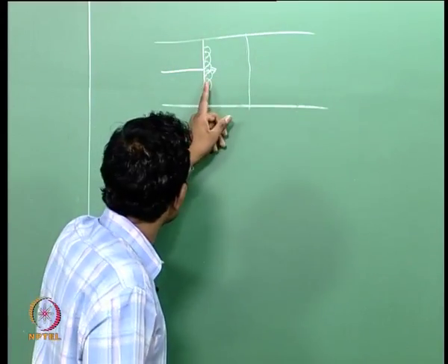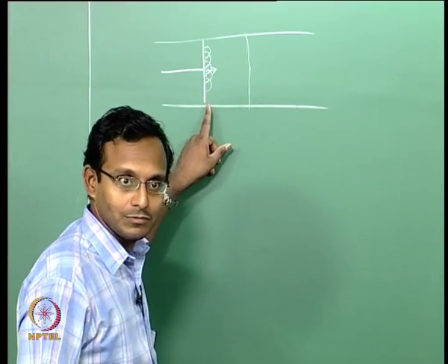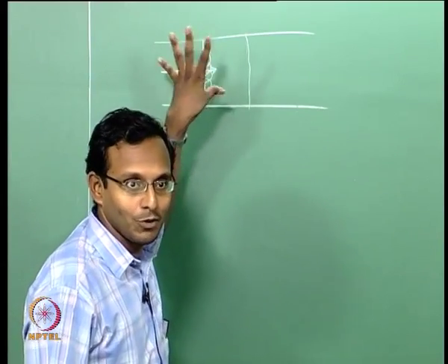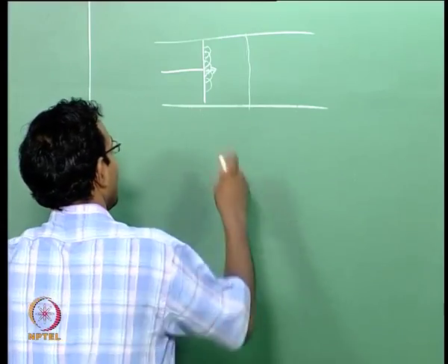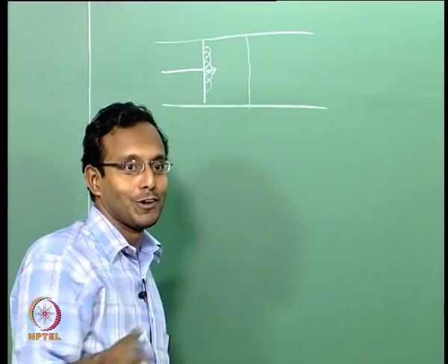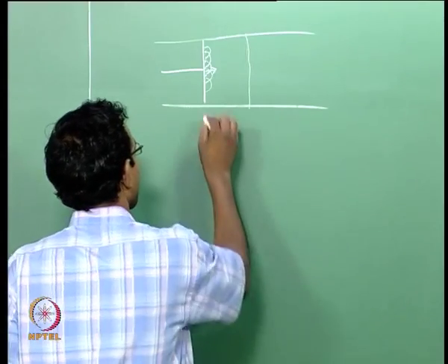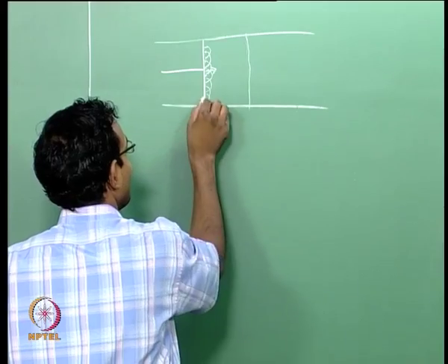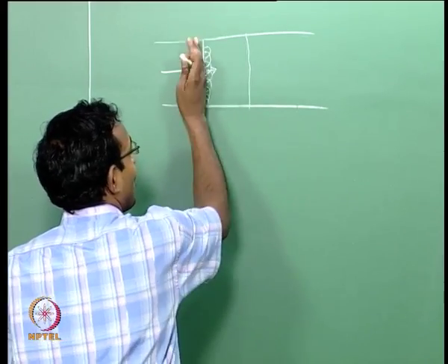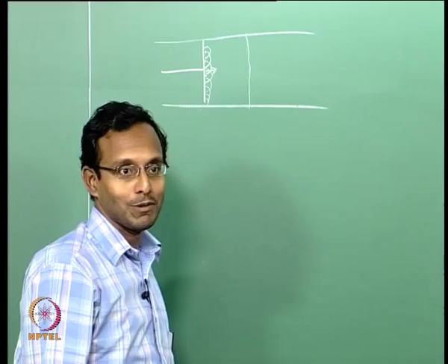Okay. Very close to the piston, it need not be true. It can go wrong. Especially with friction on the wall, it will definitely go wrong. We are ignoring friction in this whole discussion for now. Okay. So I am forming so many spherical waves next to each other, all of them interfere to form one straight line wave. That is our 1D problem.